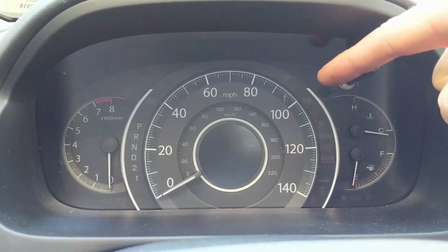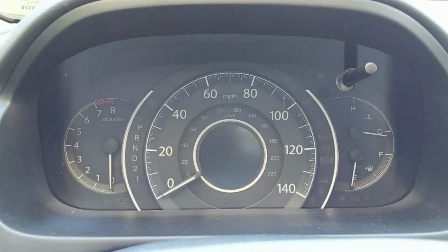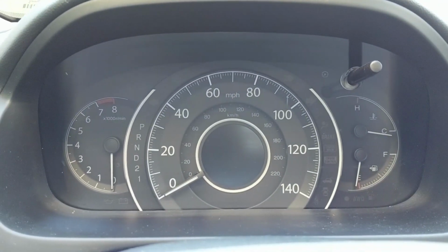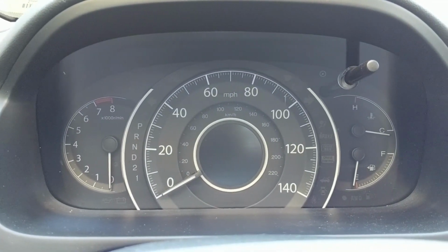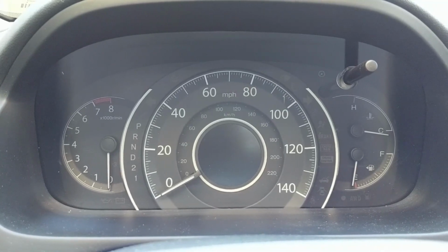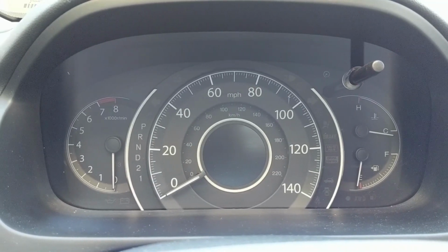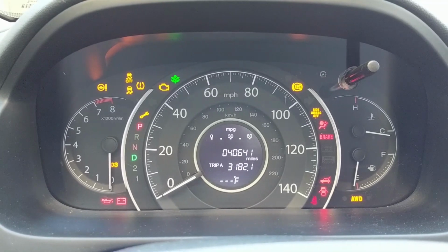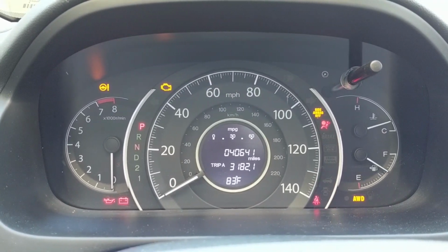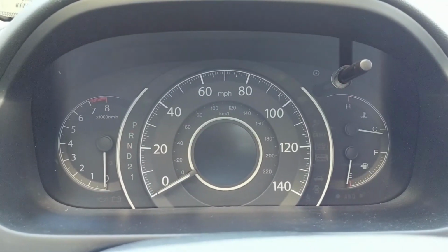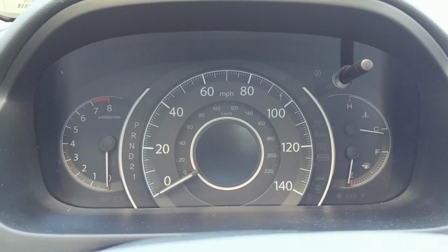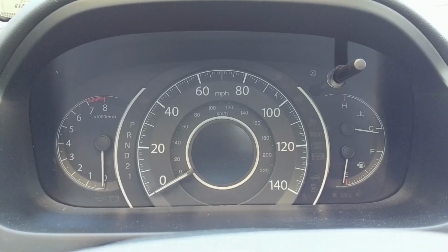Let's go take a look at one particular system on the 2014 Honda CR-V. Pay attention to a warning light right here. It's a yellow ABS system warning light. It illuminates for the bulb check and then times out when the system determines there are no faults in the system and it can turn off. ABS off. That light is being controlled by the control module itself for the ABS system.